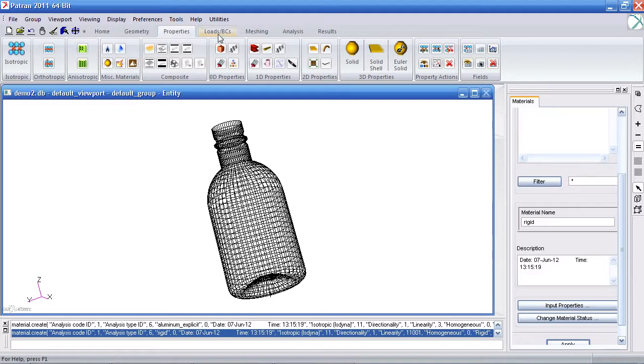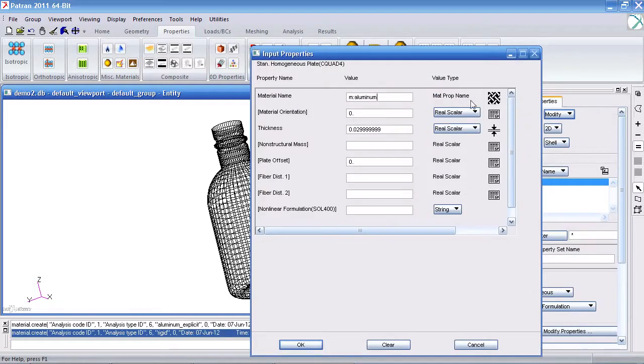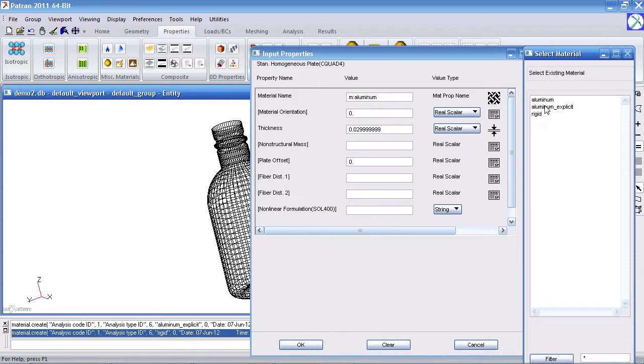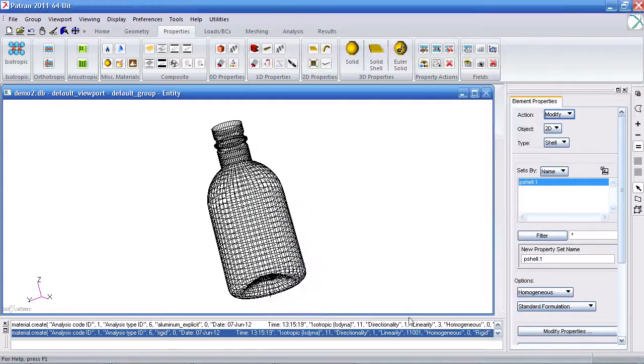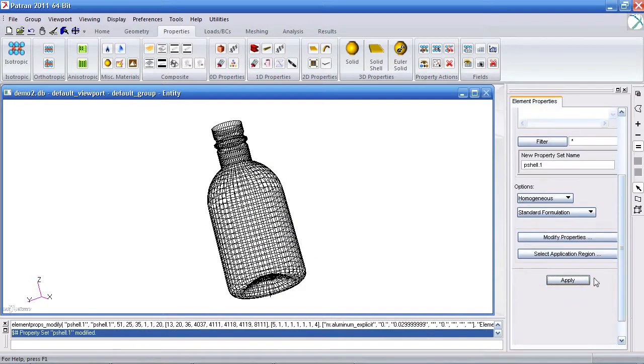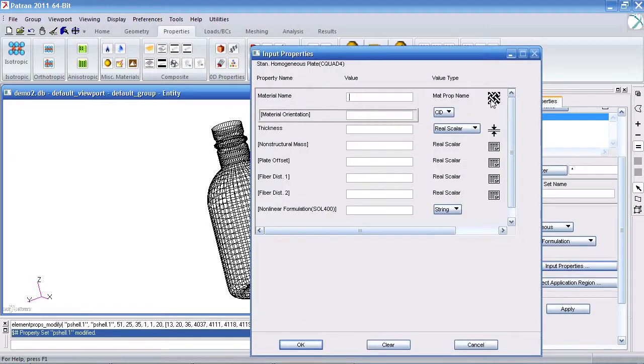We've got some shell that came in from our previous model. So I'm going to just go in and assign the newly created material to the properties that came in along with that. Now the thickness is appropriate. Still want it to be 30,000 thick, so I'm going to say, okay, that's fine. Okay? And as long as I'm here, I'm also going to create a new property for my rigid floor. And for that, I'm going to use that material that I just created. I'm also going to give it an arbitrary thickness of 10,000.